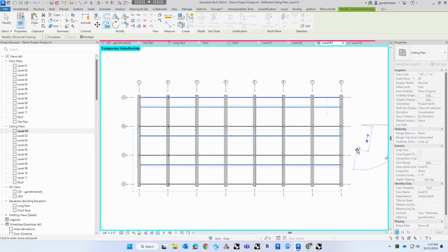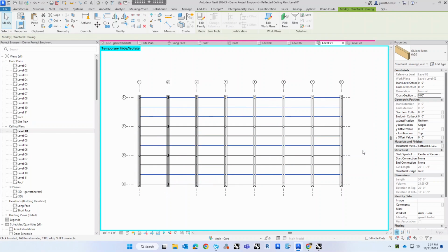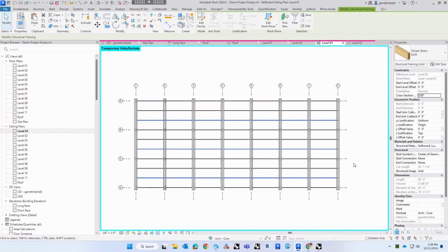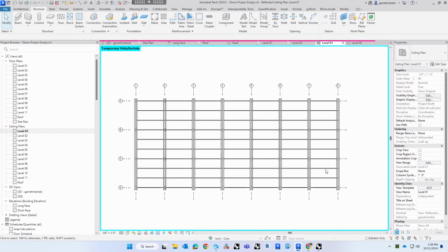Now how those are placed and how they're spaced really depends on your project. For the River District project, we actually have the purlins in a completely different spacing than the grids, and they extend a little bit past, and then the CLT stops, and the CLT actually spans over them, and it creates a really nice channel for our main HVAC systems when they're running along the core. But again, you could do it without purlins, right?